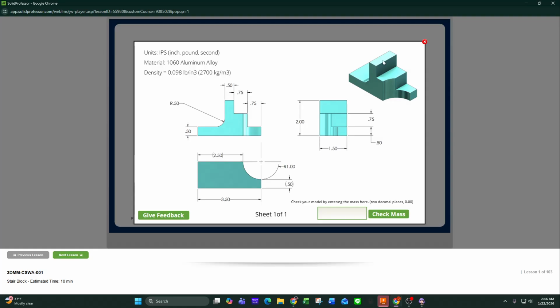It doesn't have a lot of our visible lines or our hidden lines. So again, not a fan of the way this looks, but this is just the top down. If you were looking at this from overhead, your depth is here, got a width here, the width of the whole part from edge to edge is there. And it's actually rotated, so you can see that cutout notch is this front corner here. So from the back corner here to the back corner here is 3.5 inches. This front side's 2.5. So you can start to get your dimensions here.